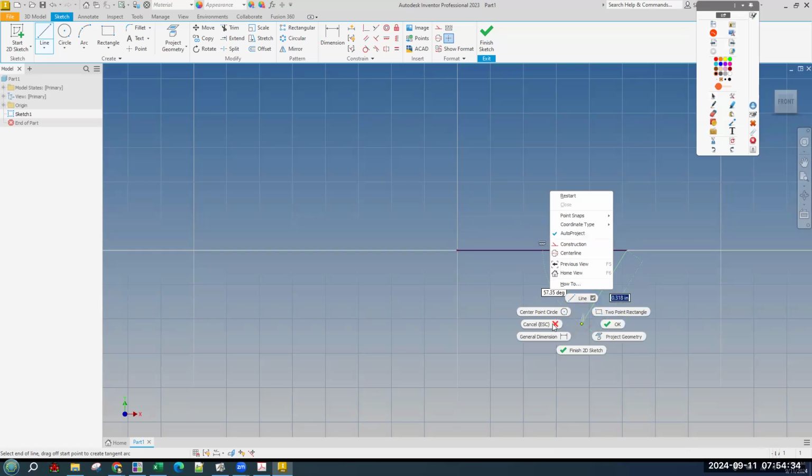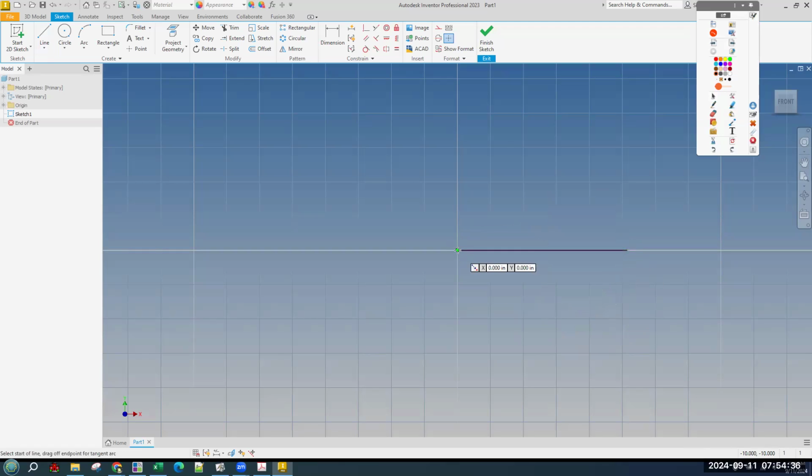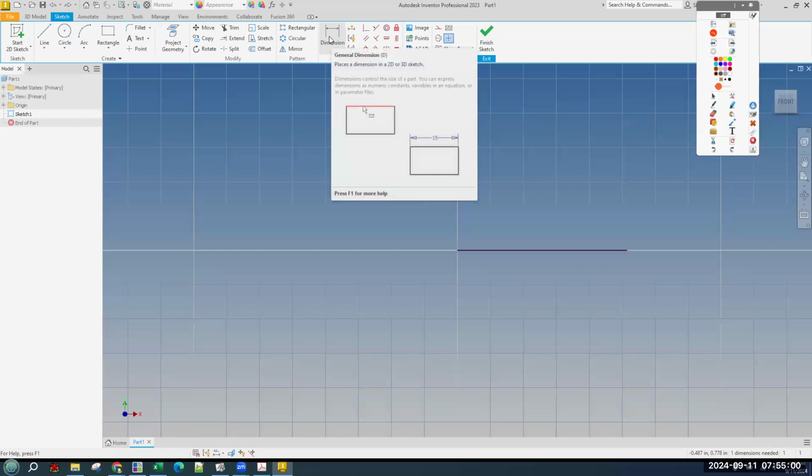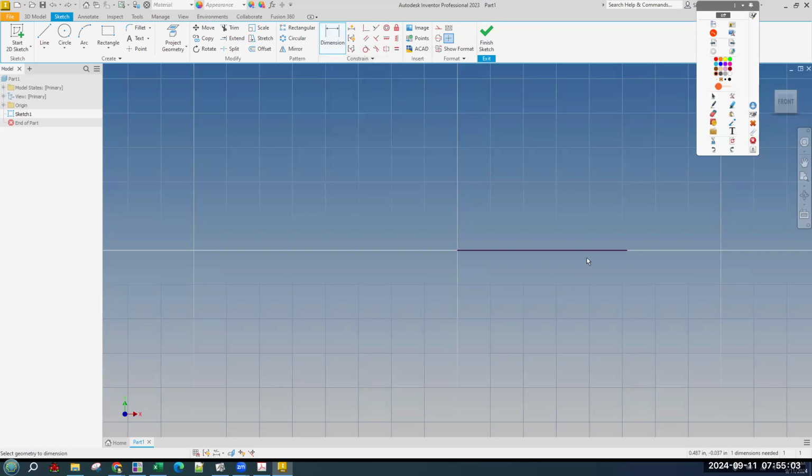I'm sure many of you just automatically did the click and drag because in a lot of applications, that's the way you make a line. But click and drag in Inventor makes arcs, which is not what we want. We just want a line. So it does have to be click, move over, click again. And again, it's make a line, dimension it, make a line, dimension it. We need the dimension tool. Click on the bottom here, click to set it, and this one needs to be 11.